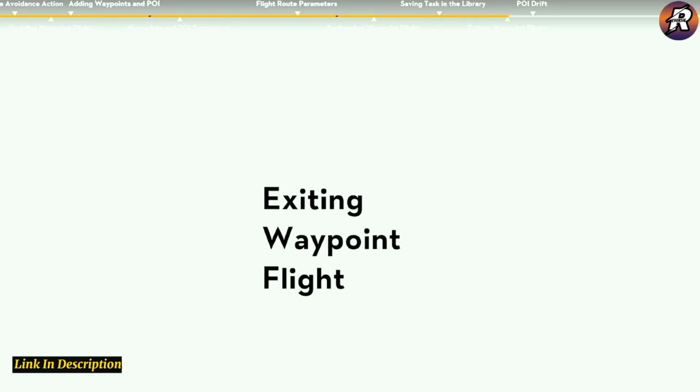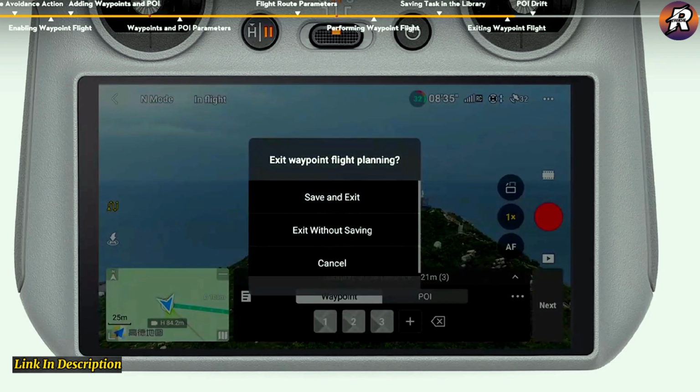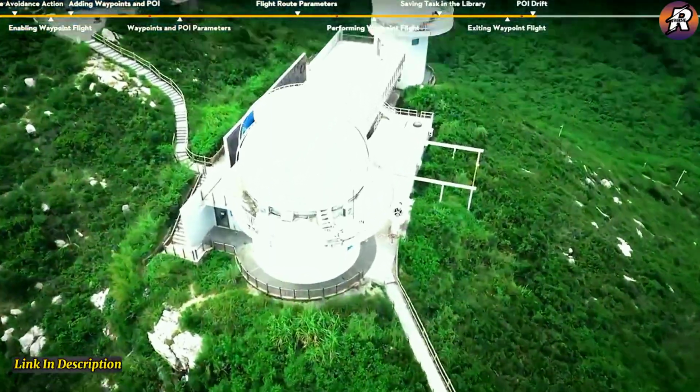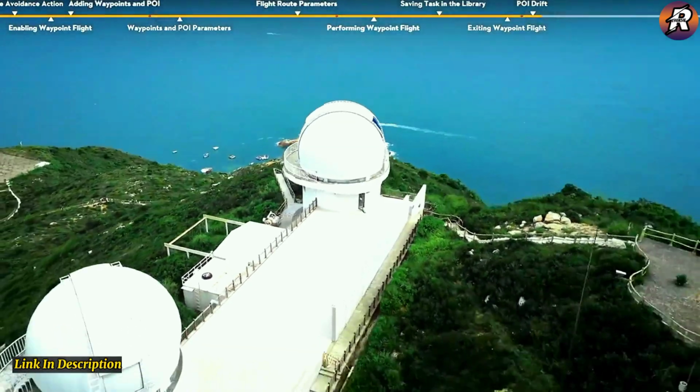Exiting waypoint flight. Tap the waypoint flight icon on the left side of the camera view. Tap Save and Exit to save the task in the library and exit. Example: POI drift. Next, let's see how to use the waypoint flight function of DJI Fly to complete a POI drift shot.